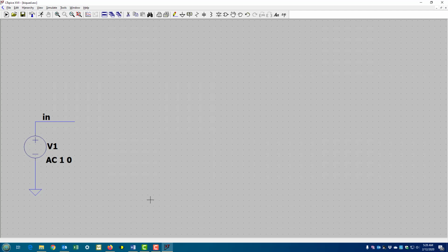build our circuit. So how do we get the components? Well, for example, resistors and capacitors we can just get from here. Up here we have resistor and capacitor. So if you click here, you can get a resistor. You want to rotate, you just say Control R. So Control R, Control R, Control R will rotate, and then left mouse button down, click it down. It basically puts it where you want, and it's still active now. You can put another resistor down. Maybe you can do Control R and put another resistor over here, for example. Click, and when you're done with putting down the resistors, right click to get out of that mode.